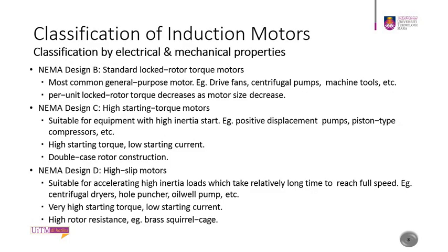In induction motors, you have NEMA classifications. They are classified by electrical and mechanical properties, for example NEMA design class B, with standard locked rotor motor torques. It's the most common general purpose motor, for example to drive fans, centrifugal pumps, and machine tools. The per unit locked rotor torque decreases as the motor size decreases.